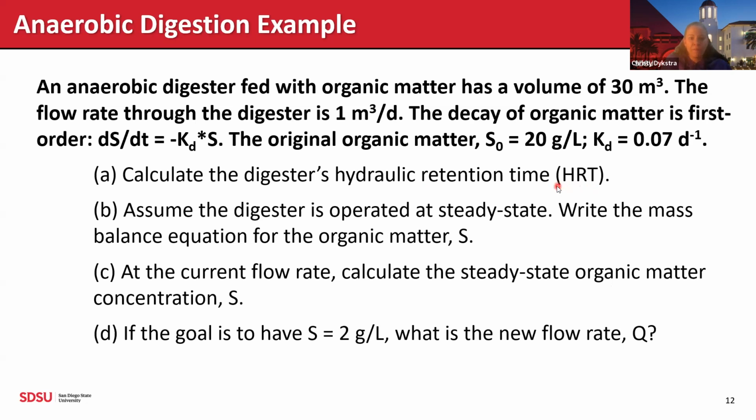So if it's a continuously stirred tank reactor, or CSTR, that means the water is going in with some of the feedstock and then being mixed around and then eventually leaving. Hydraulic retention time is basically how long it stays inside the digester. It also means that's how long this digester has to break down the material.